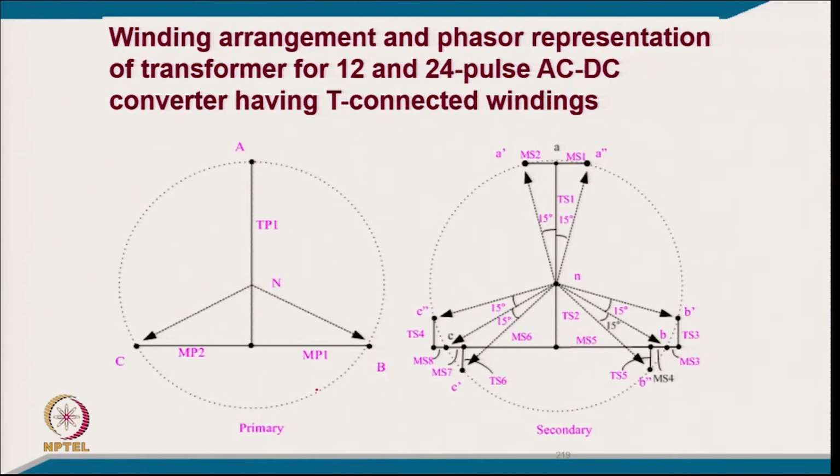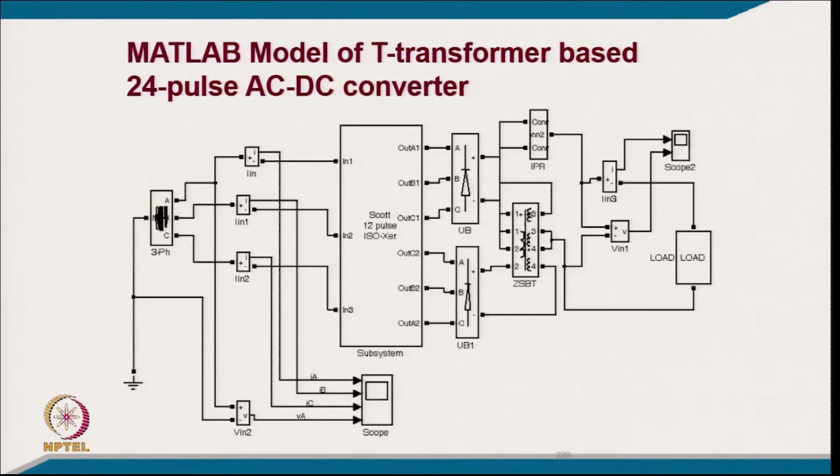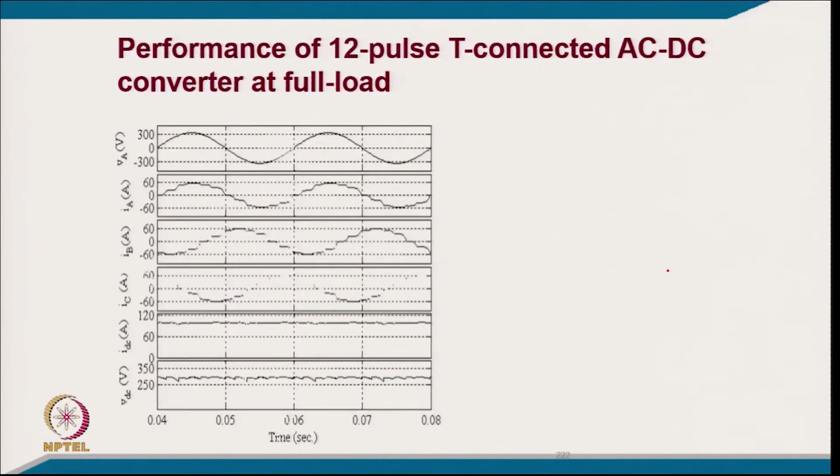Okay, you have one horizontal and one vertical, that is the typical. Neutral you do not need, but here you require the neutral just to equalize the voltage, and this is how you are getting a phase shift. Typically for 12 pulse, a 30 degree phase shift with plus minus 15 degree for one set of winding, another set, another. So, you have one 3 phase and another 3 phase, and this is typically the model of the total system, and this is the transformer connection model.